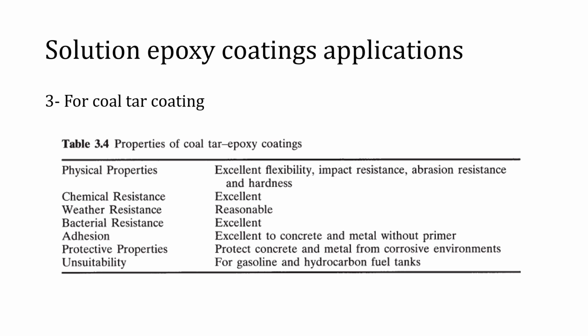The choice of coal tar pitch is significantly important to achieve a good coal tar epoxy coating. Often, in hot climates, the tar is blended with the curative in advance to avoid unwanted reaction of the tar and the base, which may increase the viscosity, and also to reach a better cohesion between the tar and the base resin.